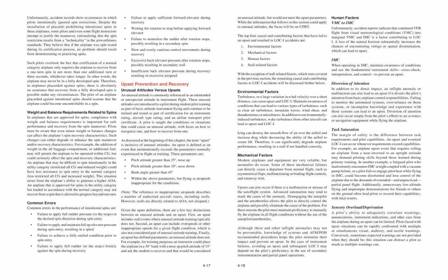Failure to neutralize the rudder after rotation stops, possibly resulting in a secondary spin. Slow and overly cautious control movements during recovery. Excessive back elevator pressure after rotation stops, possibly resulting in secondary stall. Insufficient back elevator pressure during recovery resulting in excessive airspeed.